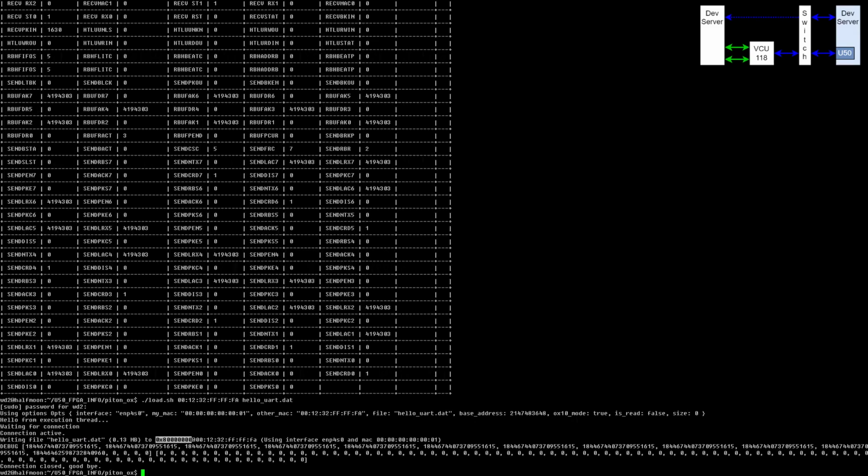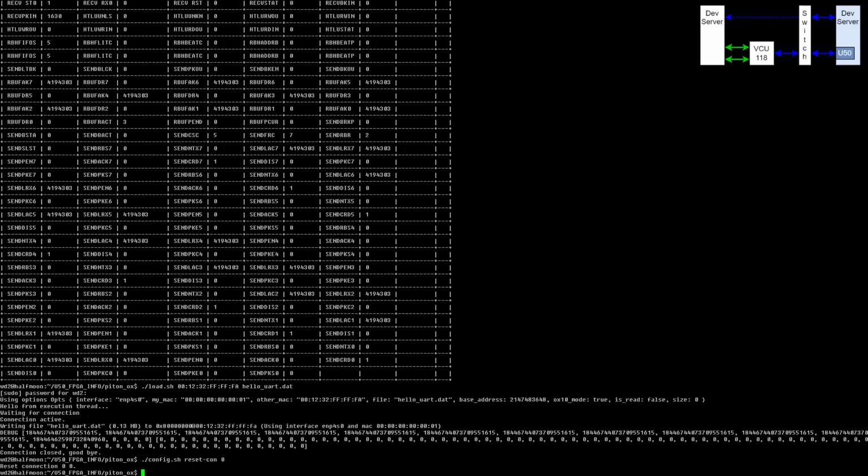The terminal output here shows that the data was written to the memory starting at an offset of 2048 megabytes. This is the address at which the CPU begins execution. Finally, to ensure that the now stale connection used to load the data is not used again, we'll reset the endpoint's connections.